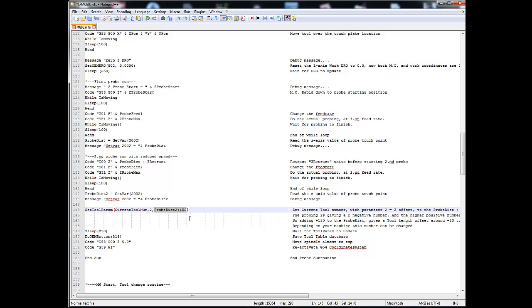Now this is some kind of a hard-coded value that I just found and placed, and that means when I look at the tool length offset in Mach3, it will be around -5 to +50 millimeters looking at the screen. And that's, I won't say important, but it's quite useful, because once you deactivate tool length offset and you have a huge length or an offset, you might end up out of bounds or you hit a soft limit or something like that.